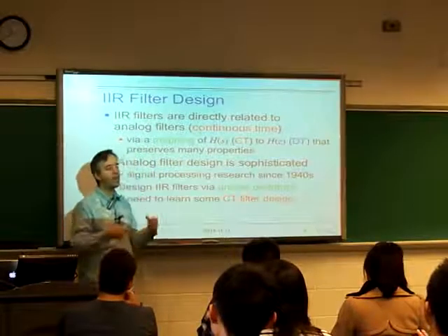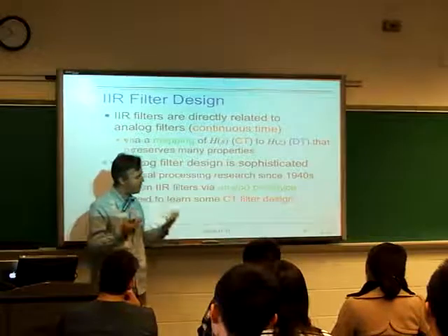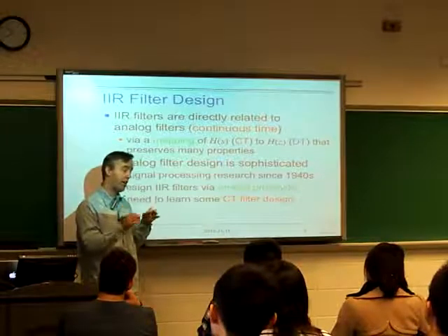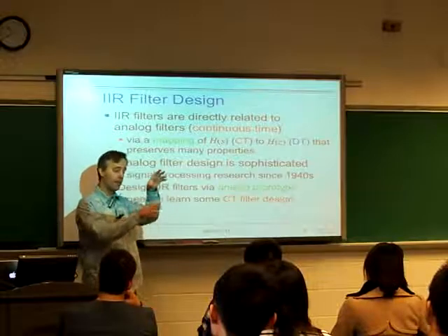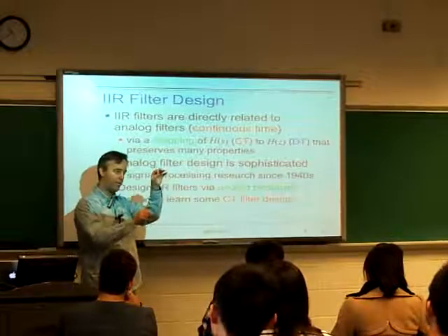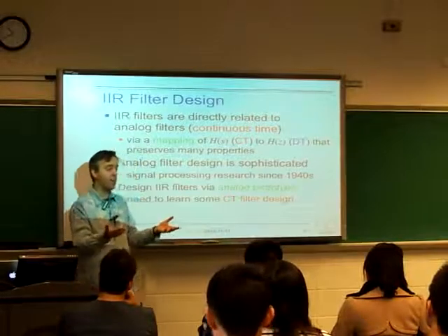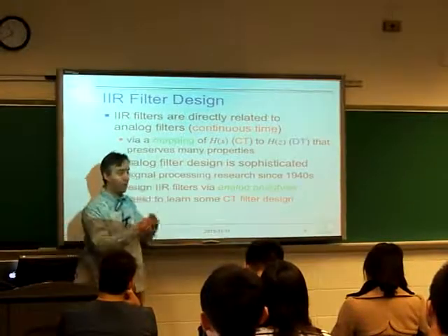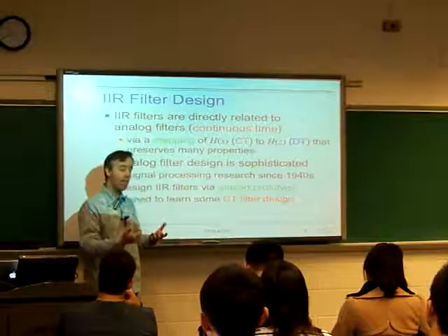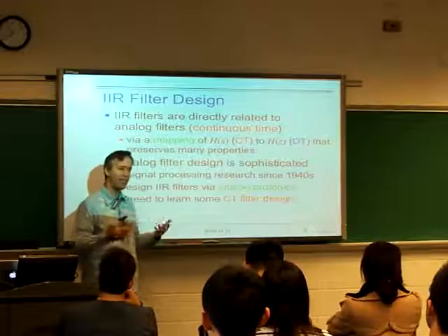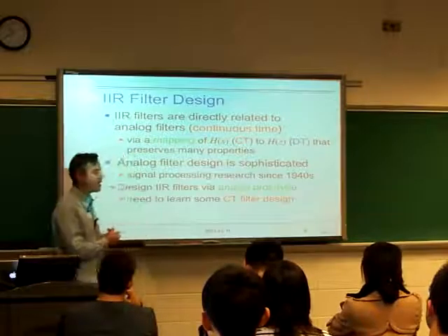So when I'm just thinking about solving a problem very simply and intuitively, my instinct is always to go for an IIR filter with some poles, put the poles where I want, figure out where the zeros go, and maybe then use a design procedure to get the exact optimal values within that family. It's a very natural thing to do. And so the FIR is a little less intuitive, and so it's a little less familiar to me.